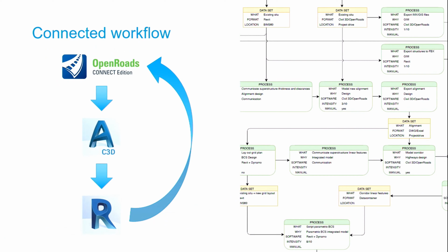Royal Haskoning designed the alignment in Bentley OpenRoads. We imported that alignment into Civil 3D using a dynamic link. You can do that when you use data shortcuts. We scripted the Revit bridge based on the alignment and based on the whole corridor model, and we could use that to optimize the alignment. The alignment was optimized about 7 or 8 times during the project. And back in the day, when there was no scripting around, you would have to remodel the complete bridge after every alignment change.